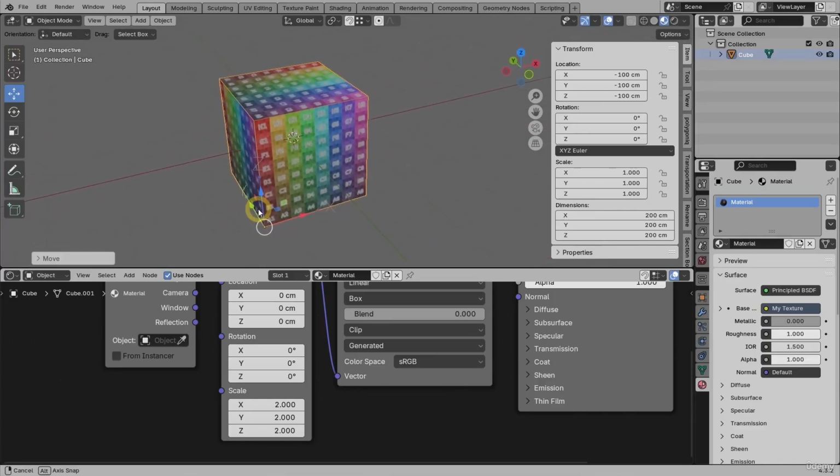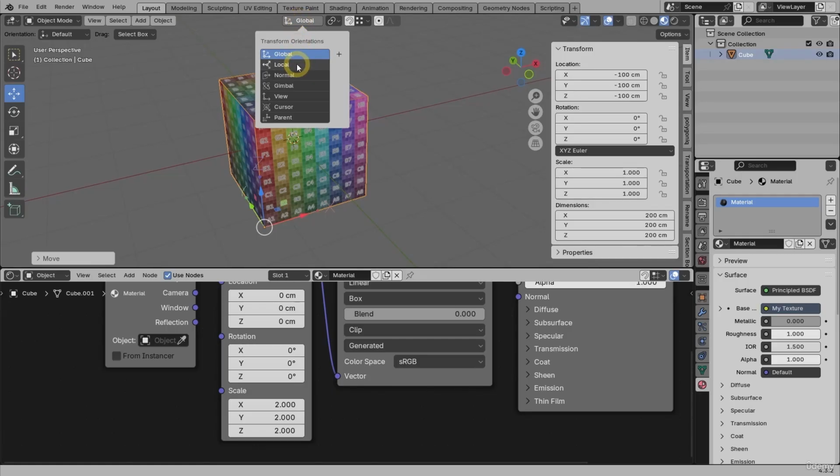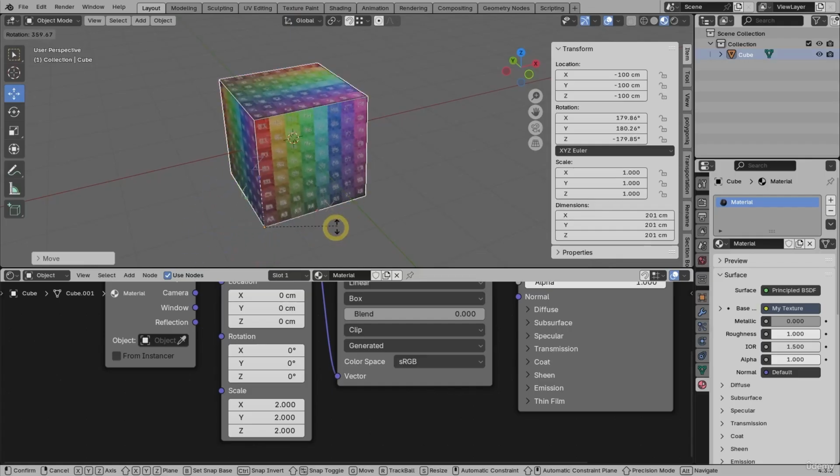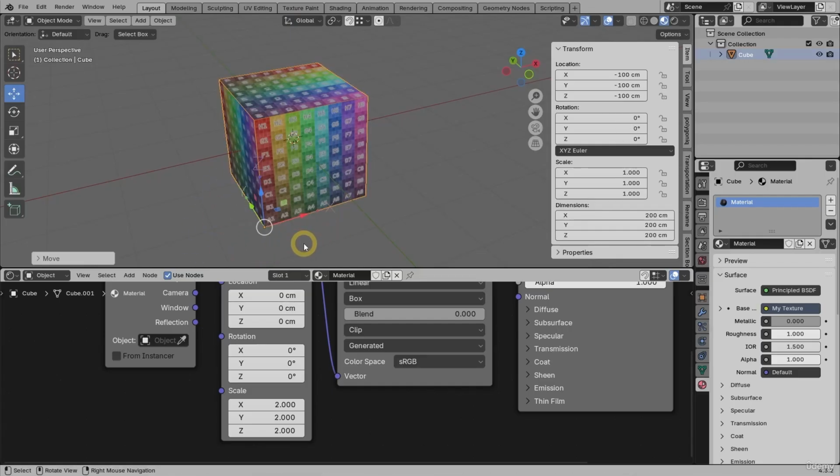of one texture tile. From this example, we can conclude that the projection is not based on a global coordinate, but instead it is based on the object's own or local coordinate. If you rotate the origin, the texture will be rotated as well. For correct results, you should always align the origin orientation with the object's surface orientation. Otherwise, you will get visible squashed or stretched textures. This is something to remember when you are doing a project, especially if part of the buildings are tilted.